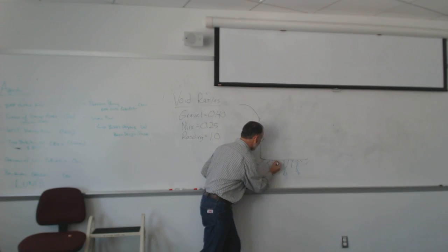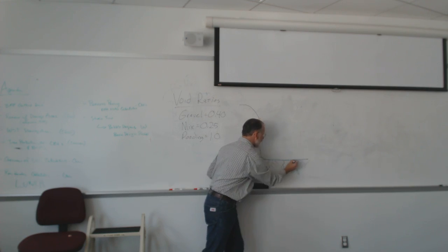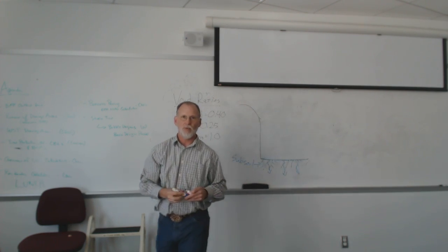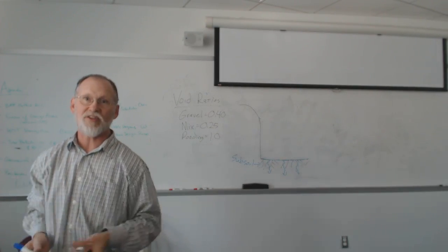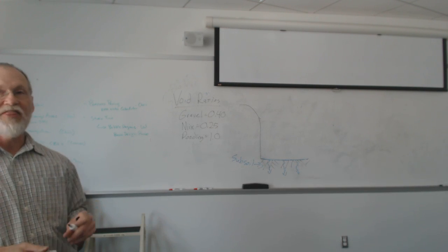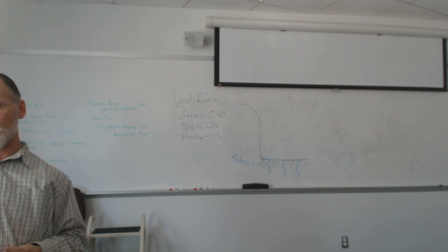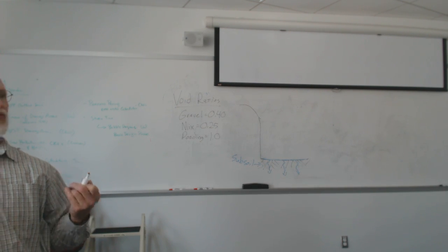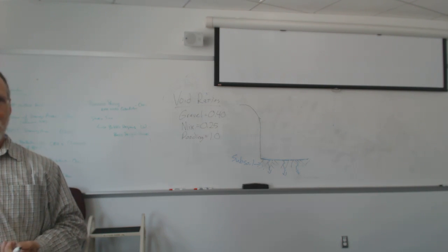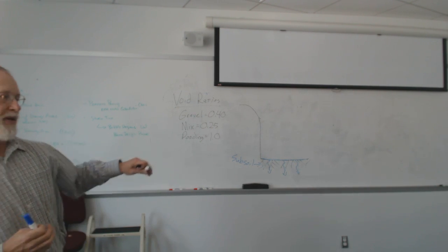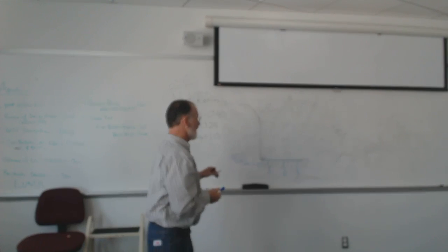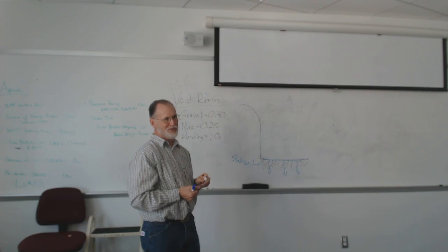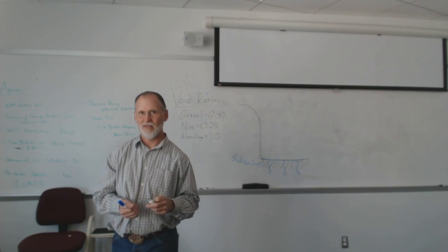So this interface right here, that surface of the dirt that you see when the guy or gal on the big machine is done digging a hole, that is the surface that your rainwater is going to see. It's extremely important that that surface be dug in a manner that is conducive to infiltration.